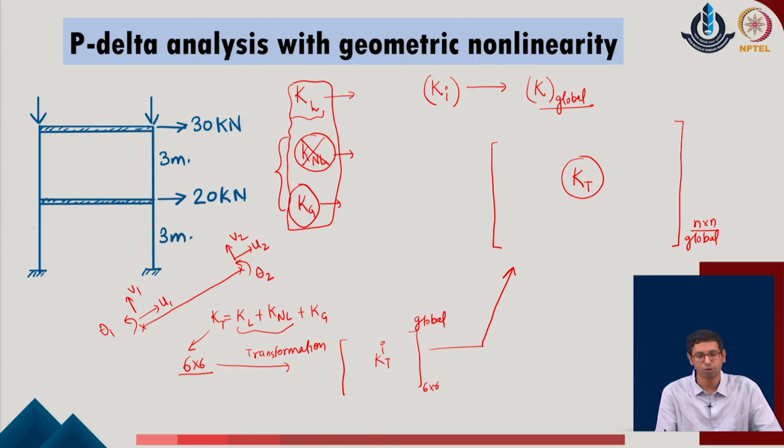One is that we do not need to consider the nonlinear stiffness contribution due to the large displacement, because in simplistic frame-like systems I can consider that the sway which is available in the system and the compressive loads which are active in the given system can all be accommodated in the Kg matrix of the given system. But other than that I do not need to generally include the nonlinear terms of the stiffness contribution in